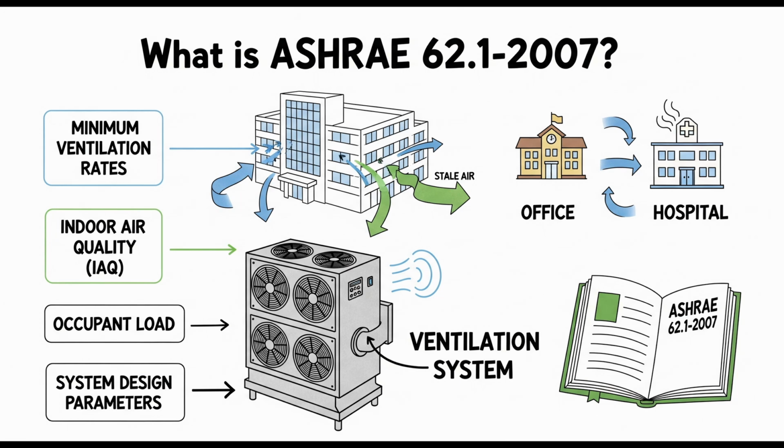If you replace a major component, like an air handler, ideally the new component should meet the current standards requirements from Section 5, though there might be exceptions for just replacing like for like if the old one met code back when it was installed. But if you do a substantial alteration, that's more likely to trigger broader requirements to meet the current standard. So even for older buildings, the standard provides a roadmap for making things better, even if you can't hit every single requirement immediately. Precisely. It's a framework for assessment and targeted upgrades.